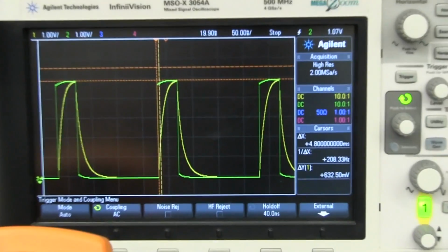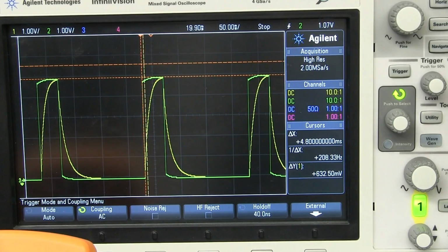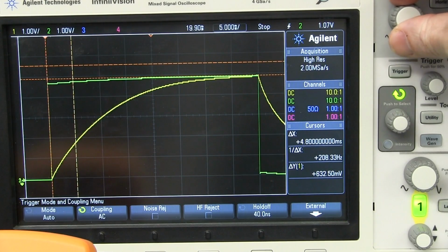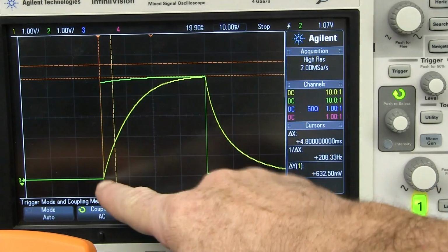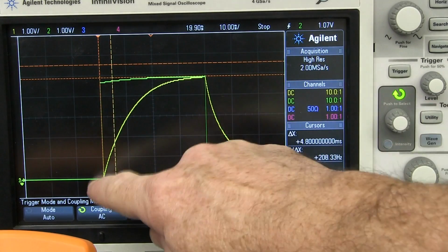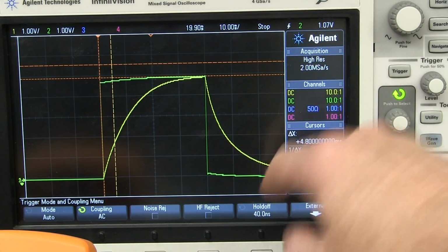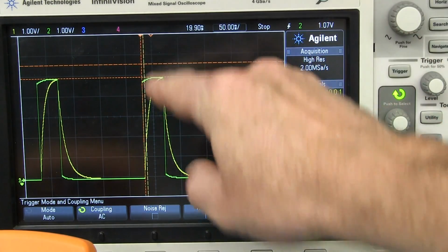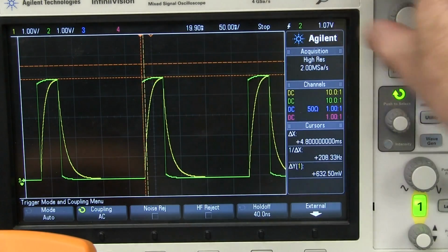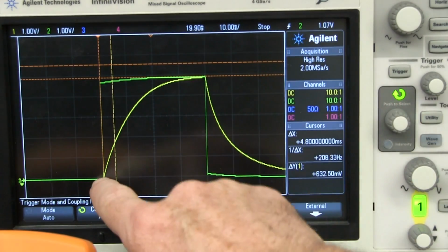And here we go. If we look at our scope here, let's single shot capture that. Bingo! There is the charging of our capacitor. Now, there's our green step change on the input there, and we're charging up until we get to 100%, and we're basically then dropping it back down, and we don't care about the discharge period here. We're only going to be looking at the charging period, so it's got enough time to charge up. So there it is.